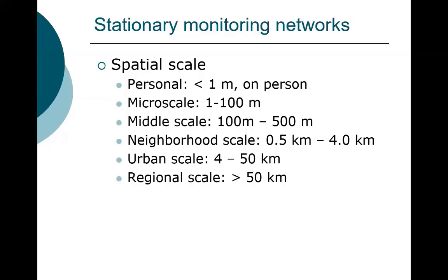So in that case, we really were looking at a micro scale. We had monitoring stations set up at the periphery of the site so that we could monitor both particulate levels and also metal levels. It was copper, nickel, chromium. We needed to measure those on the particulates to ensure that the population in the surrounding area was not exposed to these toxic metals.